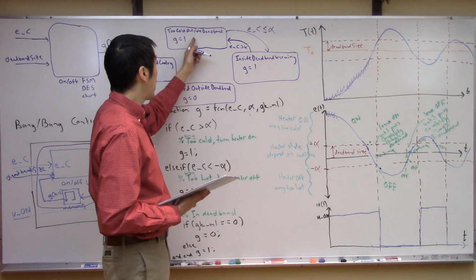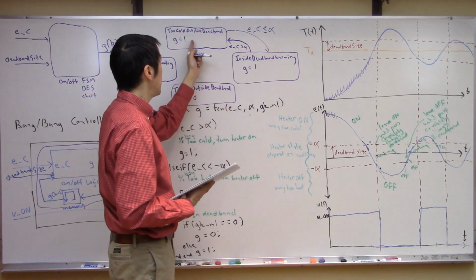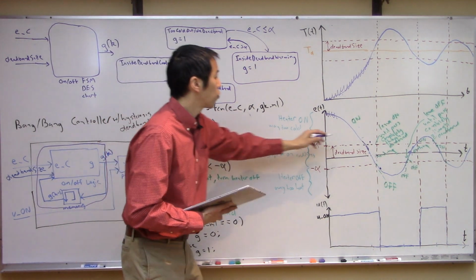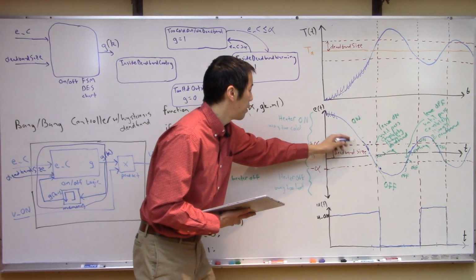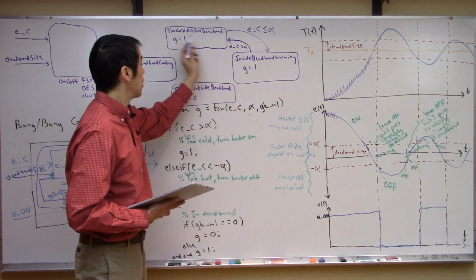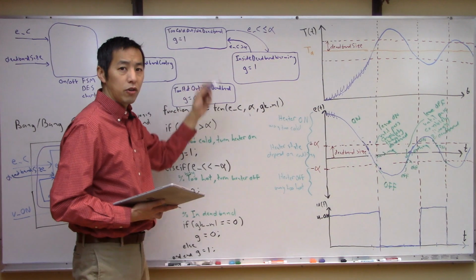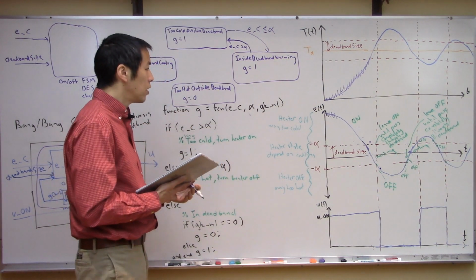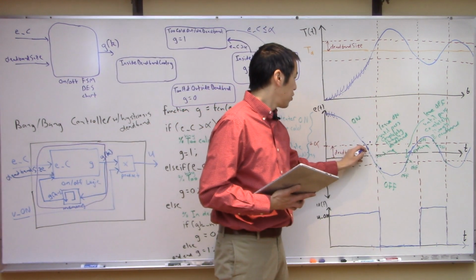And the reason it's fine is it doesn't matter if you rapidly bump between these two states. If you're chattering between these two states, you're right here on the line and you're going bump, bump, bump, bump, bump, it doesn't matter, because the heater is on. You're sending the same control signal to your actuator, so it's going to be totally fine. Okay, so anyway, you're in here.